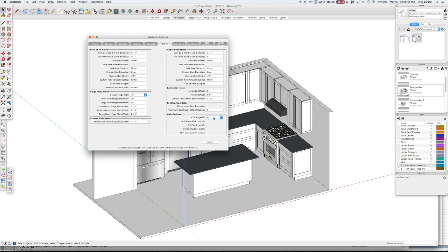And if you are on a CNC project, we can selectively drill the holes. So we won't just drill a whole bunch of holes in there. We'll only drill holes where needed for hinge plates, drawer slides, and shelves. So in that case, this parameter applies for your drawer slides. You have to know the distance between the holes on the drawer slide. So 480 millimeters is common for a 21-inch slide.